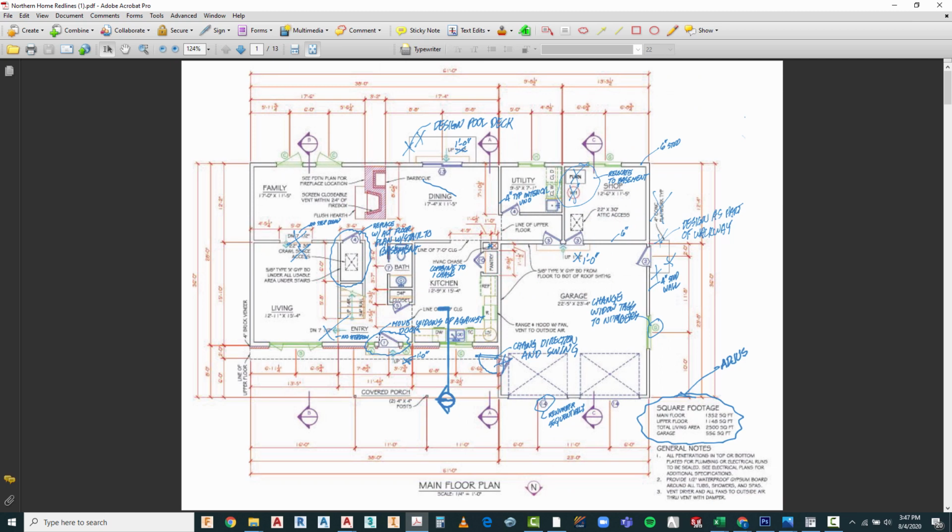The majority of the house here is at what we call our benchmark elevation. It's 0 for that level. Our garage, however, even though it says 1 foot 2 inches down, we're going to make it 1 foot. The same thing applies to the covered porch and to eventually what our pool deck is going to be in the back. So we have a slab, or a floor structure, that will wrap around here like an L all the way around, and that will be at the base level. We're going to give it a depth of 10 inches.